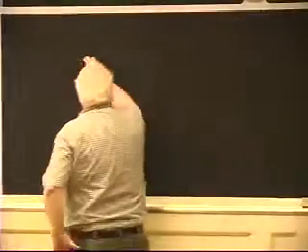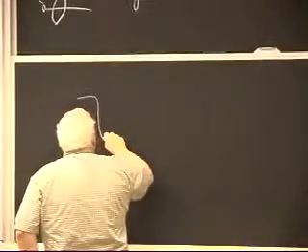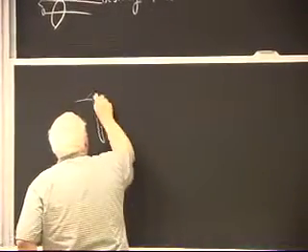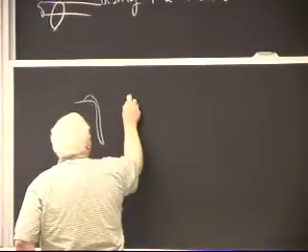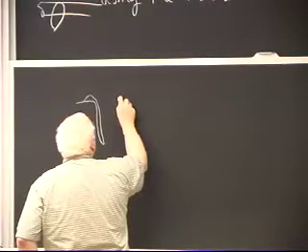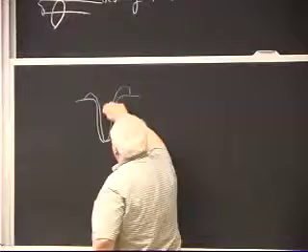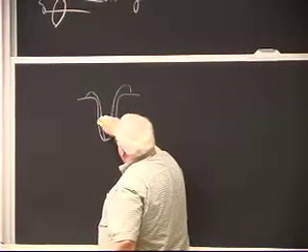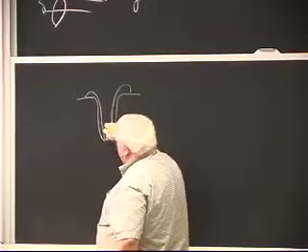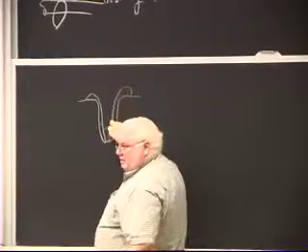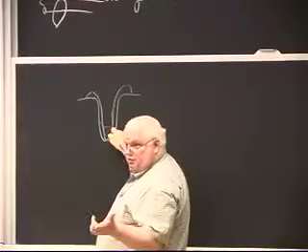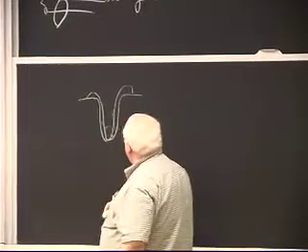Okay. Turns out the electron beam gives 30% deeper penetration in the horizontal position, and that's because I've got this deep weld pool. If I'm using the capability of having a deep surface depression in my material, some of it's humped up here, and every now and then some of that will slump in the vertical direction and fill up the bottom of the hole, and that ends up creating defects, and you saw that in the movie of electron beam and laser welding.